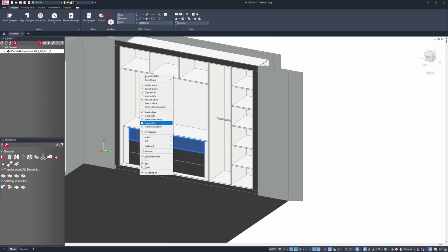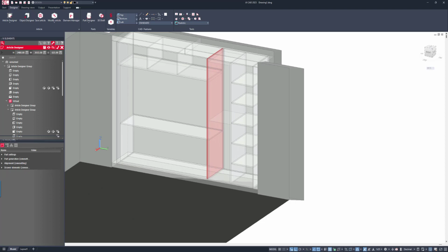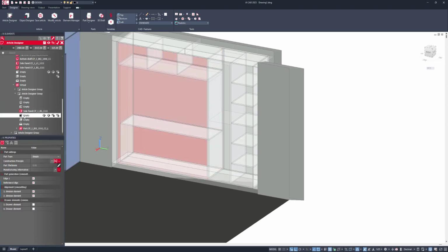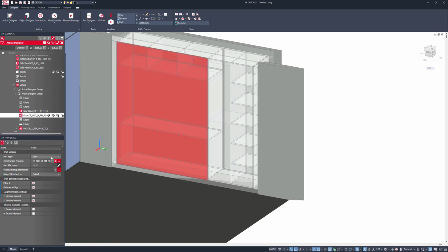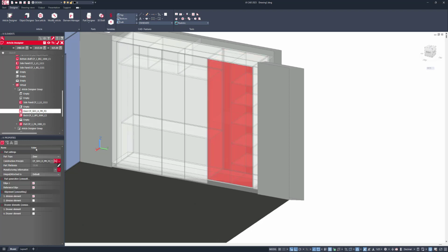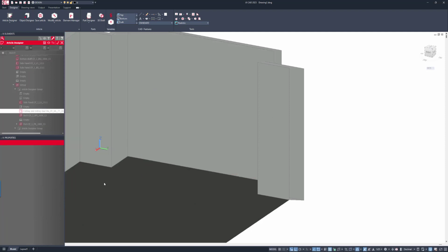Okay, let's go and add in those doors. So I'll go to this section here and add in a door over all of that. So I'll click on the tick, change to be folding and sliding, and then change to be a 4-section door. And then what I want to do is go to the other side and do the same thing, add in the door, folding and sliding, and this will be a 2-section door. Now that I've got this set,